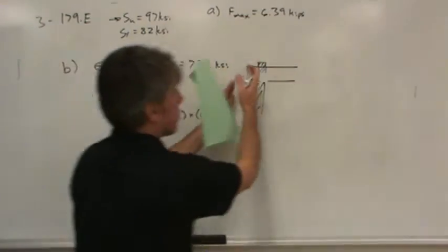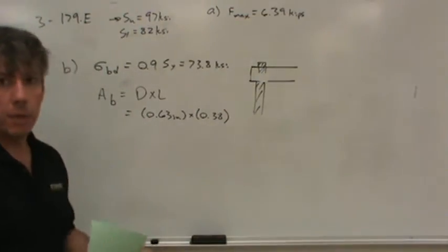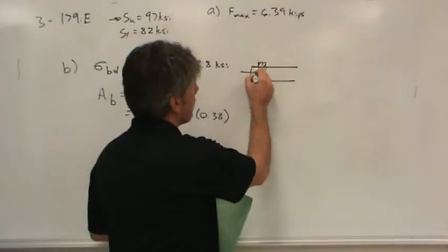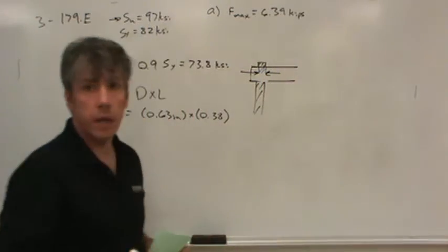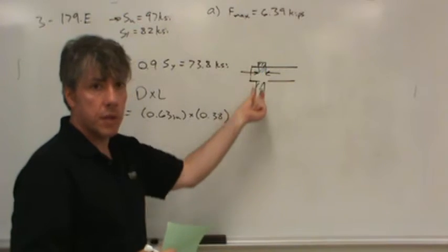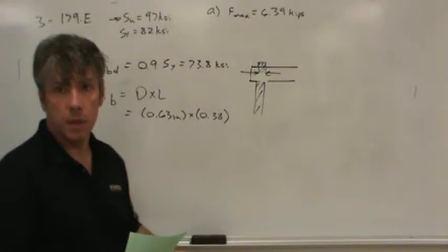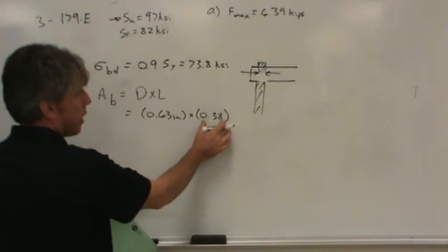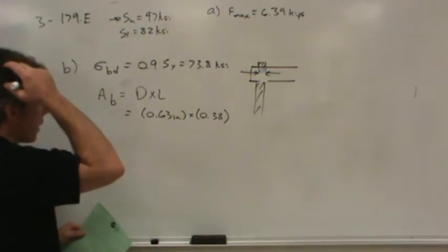The length of the pin goes all the way across, but the area we're interested in is only in a certain area of the mechanism, right? It's in the width of that side plate. Does that make sense? So that's the length where we have area and we're actually applying a surface force.